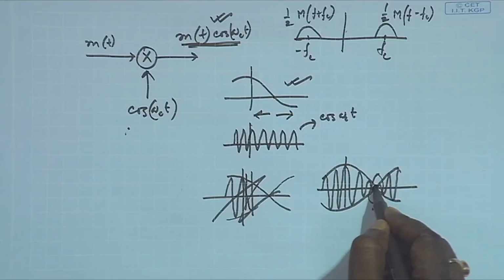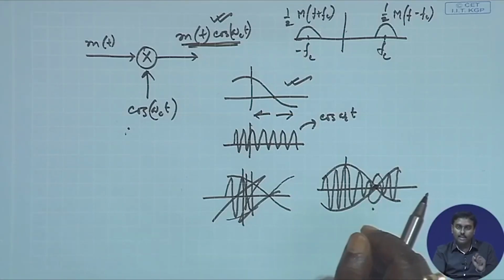So, wherever there is a zero crossing in this DSB SC signal in the time domain, if you observe the signal, you will always see a 180 degree phase reversal. Whichever way it cuts, it will just be a 180 degree phase reversal. So every point you will be getting that. That has a huge implication. We'll see that, that makes the demodulation very costly. We'll come across that, and that's where the suppressed carrier and non-suppressed carrier come into the picture. We'll come to those things.